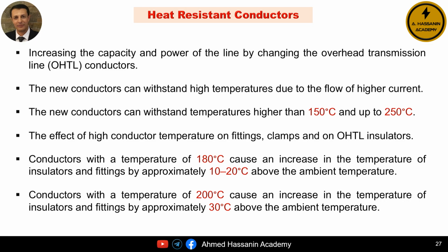However, it is extremely important to maintain the same level of sag in the new conductors. For this reason, new conductors known as heat-resistant conductors were developed. In general, these are conductors that can withstand high temperatures, typically above 150 degrees Celsius, and in many cases up to 210 degrees Celsius, 250 degrees Celsius, or even higher. By using these heat-resistant conductors, it is possible to increase the power transfer capacity or line loading capability by more than 50%. However, a very important question arises.